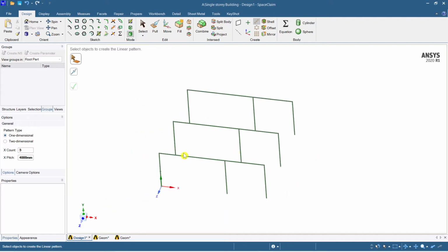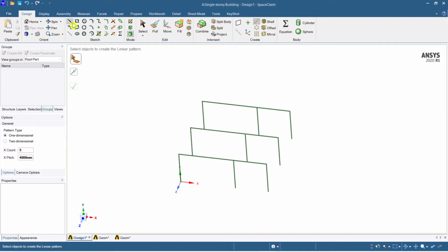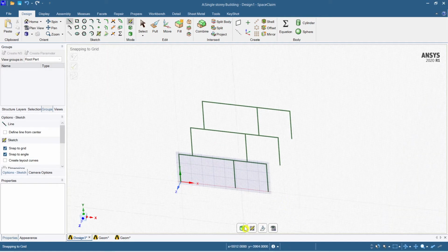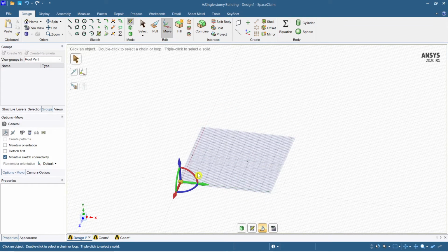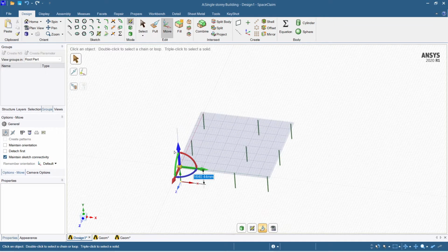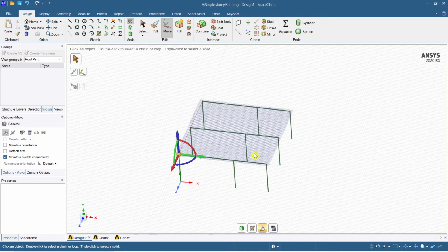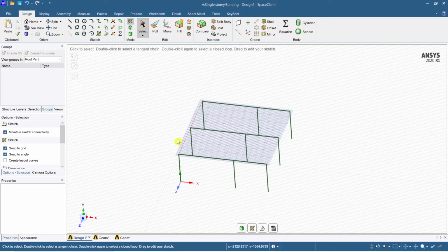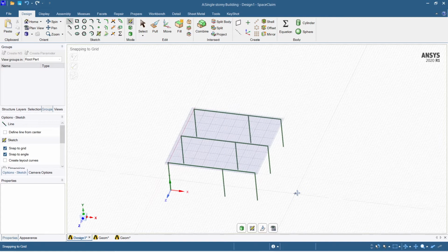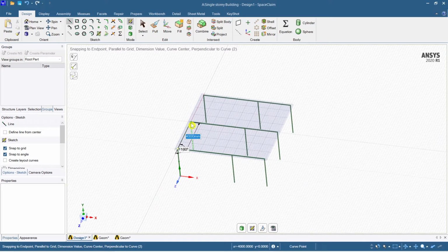Now I'm going to create the side beams here, the longitudinal beams. For that, select the rectangle here, select the ISO, and select this path here. Pull the drawing command by 3000 mm, which allows you to connect the nodes directly. This will be a time saver for us. Now the same thing, repeat.